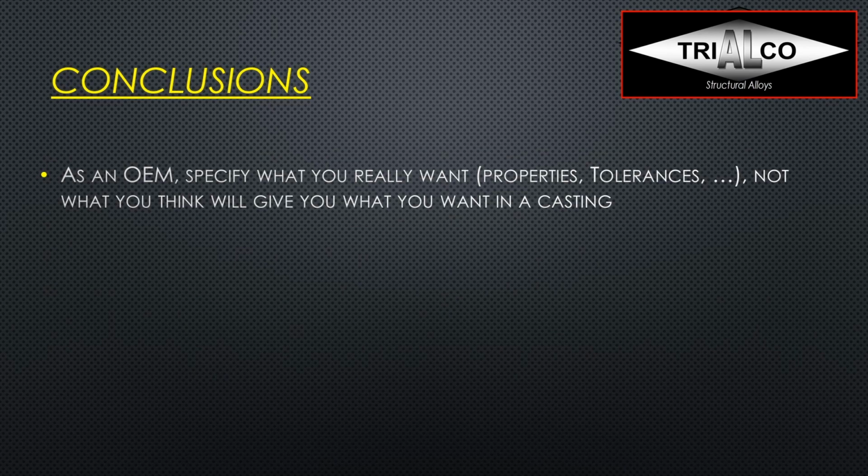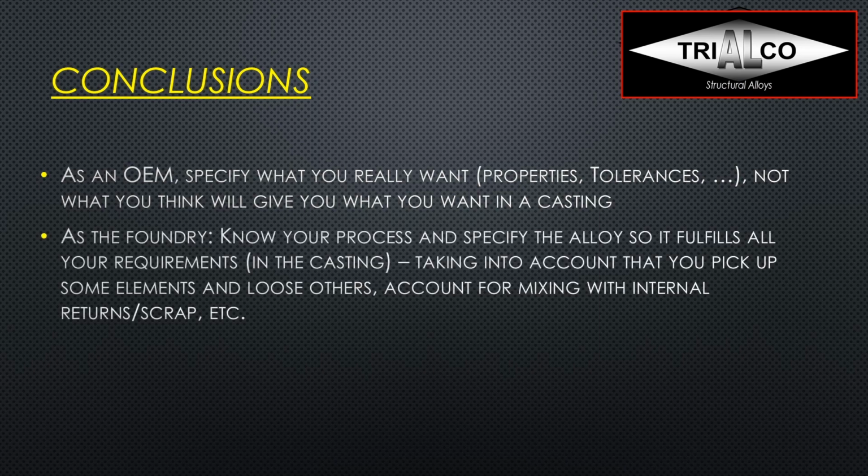As an OEM, please specify what you really want. So specify properties, tolerances, anything, but not what you think will give you what you want in a casting. Specify what you really want. And as the foundry, know your process and specify the alloy so it fulfills your requirements in the casting, taking into account that you pick up certain elements like iron, you lose others like magnesium, and account for mixing with internal returns, with scrap, etc.